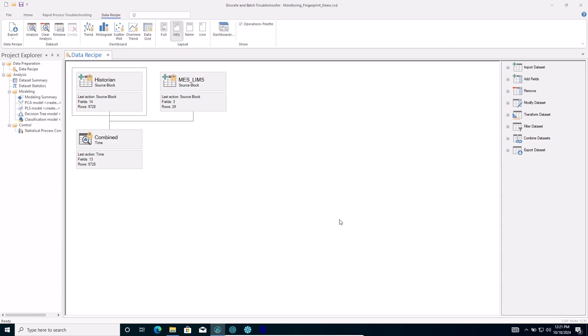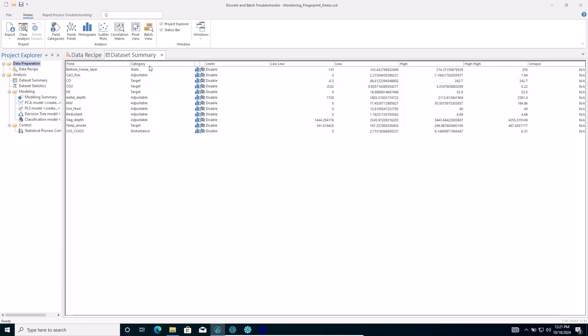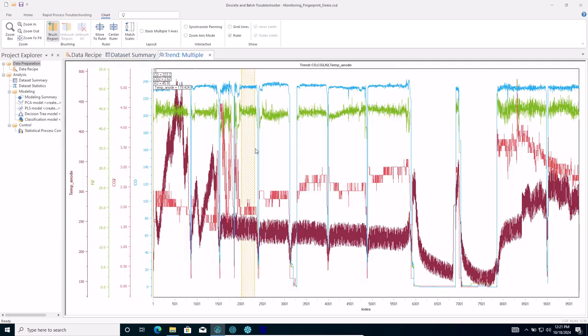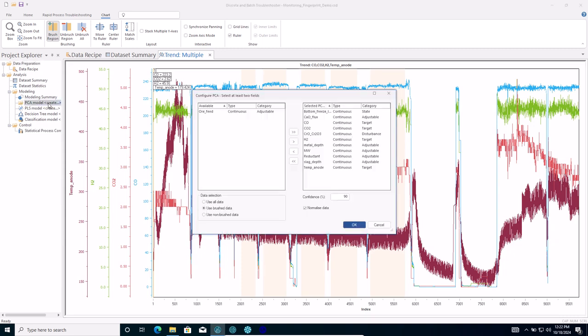In this case, I can use CSense to visually select data which represents good, optimal, and stable process conditions by marking the data that represents good behavior of the process that I want to use to make a fingerprint of good behavior. Then I can use a multivariate machine learning model called principal component analysis to create a fingerprint by using only the data that we marked as good.